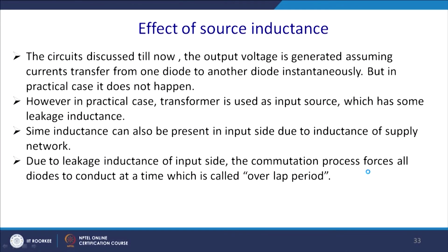So, now let us come to it. We have tried to discuss by the mapping that THD decreases due to the source inductance, because it tries to make the current continuous, the discontinuous conduction mode tries to diminish, and thus it has been reflected in the THD. But you pay the penalty of a low power factor with high source inductance. So, whether it is beneficial or detrimental, let us see that.